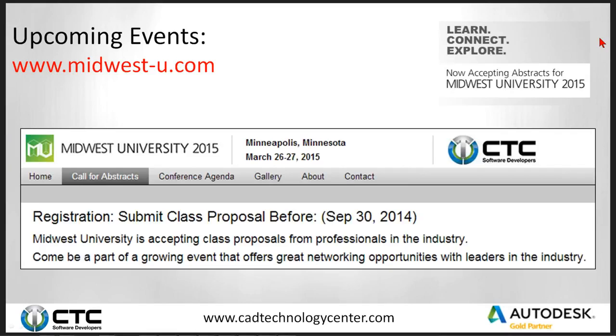And then I forgot the one part when they were asking about adjusting arrowheads. Yeah, I could have come in and actually changed my arrowheads to, instead of being a solid fill, being a hollow fill, or being just crow's feet. And yes, that command to add the default text height was actually text size. So whoever sent that in, I thank you. Again, don't use standard text anyways.